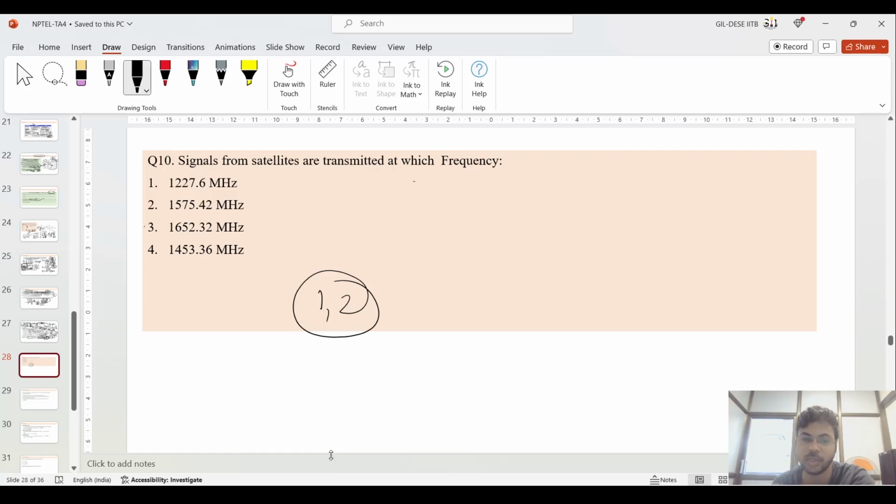You should always take this cutoff frequency, because you have to make the problem such that you pass the frequency which is lower than that, and you should not pass the frequency which is higher. So if you are designing for 5000 to not pass, you have to take the cutoff frequency lower than 5000, that is 2000. I think I have given the answer to your question, Nirni.